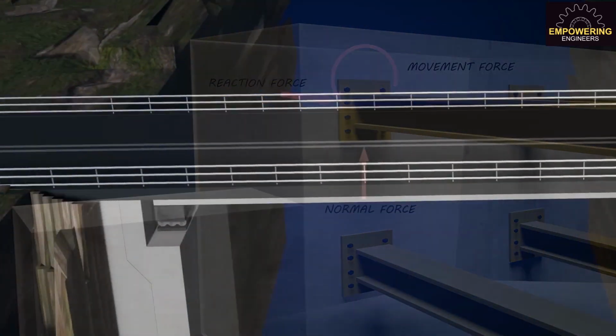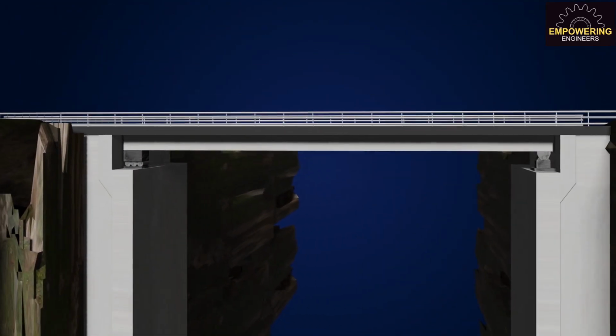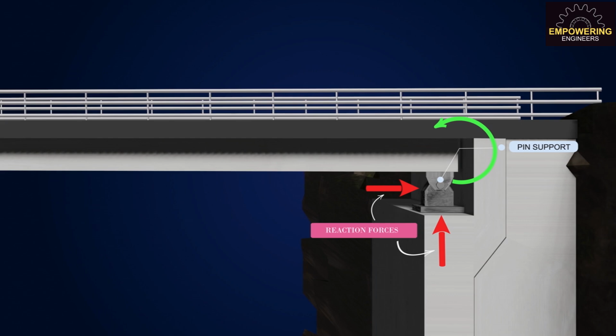Bridge structures have pin supports at numerous joints. As a result, the structure can rotate but cannot translate in either a vertical or horizontal direction. Both vertical and horizontal reaction forces are provided by these. Bridge positions are slightly adjusted by large bridge pin supports under high wind loads.